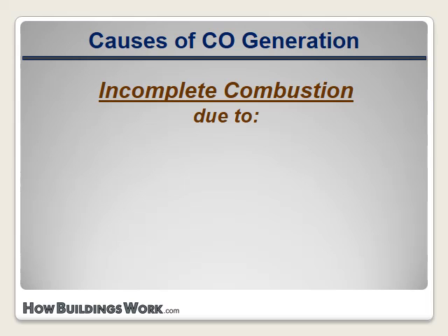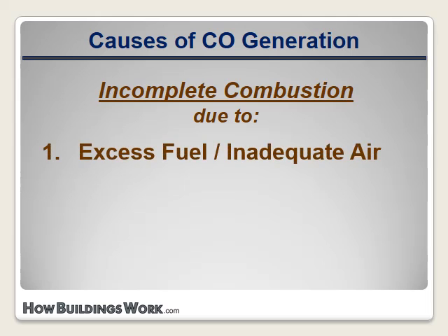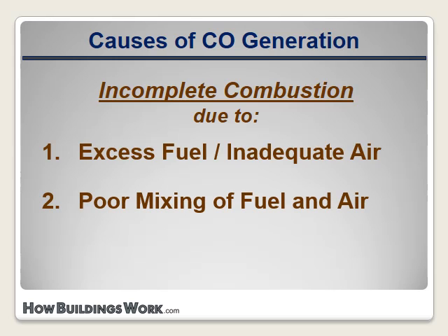There are three broad categories of situations that can result in incomplete combustion. The first is a fuel-air mixture that's rich, meaning that there's not enough air present to completely burn all of the fuel. The second scenario is poor mixing. There may be plenty of air present, but it's not thoroughly mixed with the fuel, so there are pockets of fuel that don't get enough air. The third scenario is a flame that's too cool, making it difficult for the carbon to bond to the second oxygen molecule.